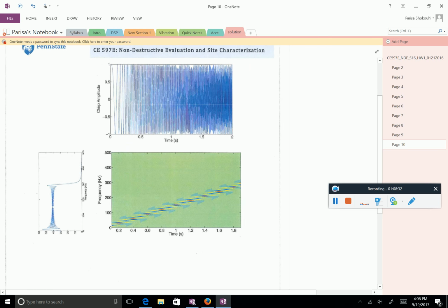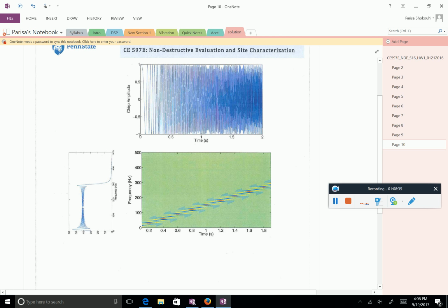This one, I think most people did a nice job. Some of you did not plot the spectrum. I don't know why. So the function is such that it actually goes on to 2 times 150. That's how the MATLAB function works. And here you can see how the frequency is changing linearly with time. Here I just wanted you to understand how to use a spectrogram. There are details about chirp, why it looks like that, because there is a lot of manipulation with the phase of the components inside. But that's not really important for the purpose of this class.